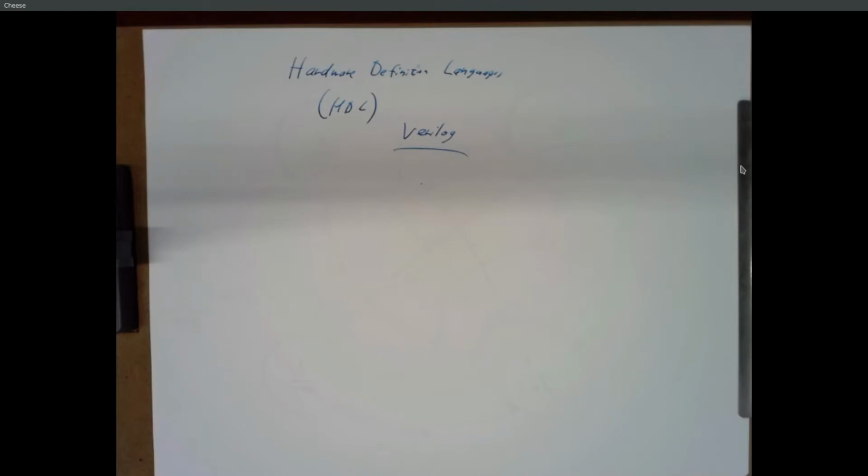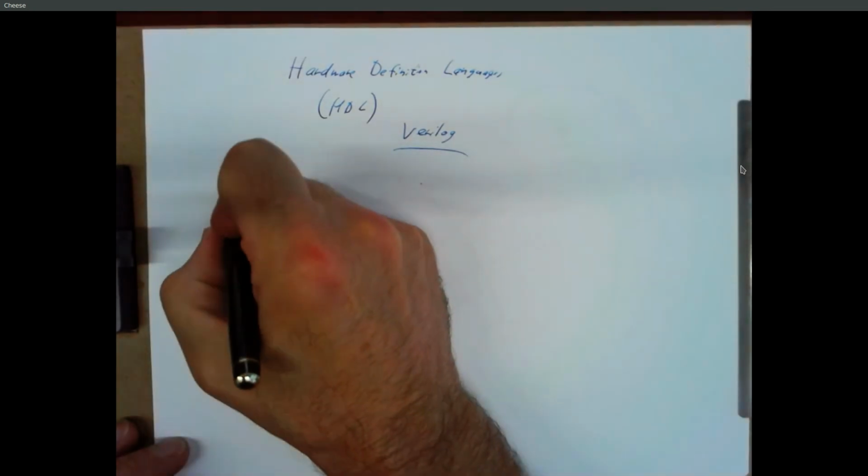When you write something in Verilog, you are describing a piece of hardware, and it's a huge difference. If you completely ignore that difference, sometimes it doesn't matter. You can think that you're writing a program and you finish your code and it works great. But when it gets really tricky and it's not working at all and it's really confusing, there's a good chance it's because you're mixing those two things up: writing a program to implement an algorithm versus describing a piece of hardware. Everything we do in Verilog is basically describing a piece of hardware.